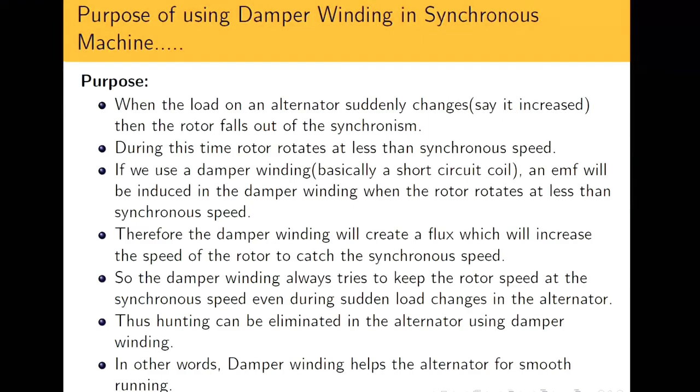So when the load on an alternator suddenly changes, let us say it is increased, then the rotor falls out of synchronism. That is, when load increases, obviously the speed reduces. During this time, the rotor rotates at less than synchronous speed.